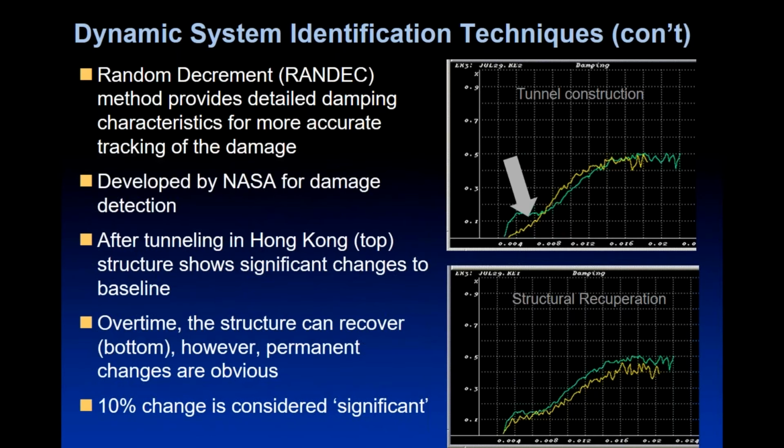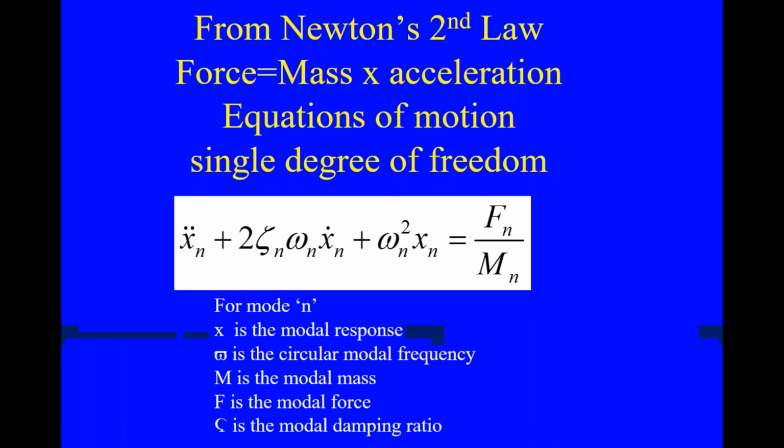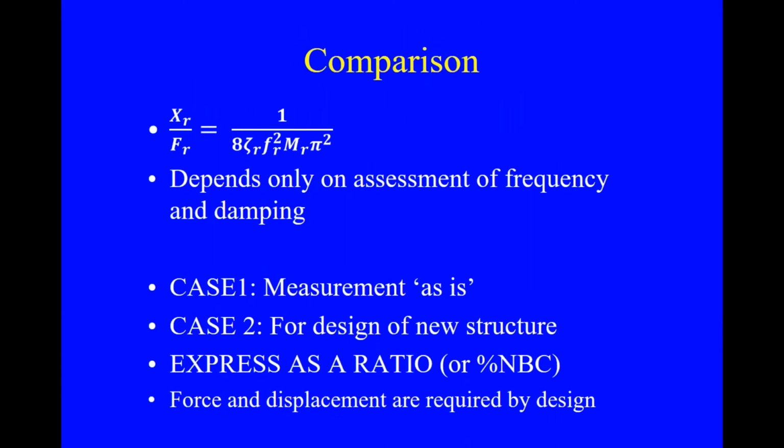We looked at it and we looked at the characteristic 1 month later and found that yes, there was damage that shook the building up and made things come apart, but they recuperated. They re-established themselves, but now the rate of rise of damping has changed and the overall capacity has reduced by 10%.